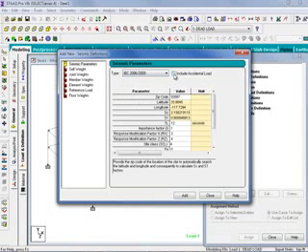Adjacent to the code selection, we will find our Include Accidental Load checkbox. The accidental load parameter prepares STAAD.Pro to calculate and apply torsional loads to account for code-specified accidental eccentricity. In STAAD.Pro, you can only include one seismic definition per model, so if any of your seismic load items wish to include accidental load eccentricities, you should select this checkbox. We will then complete the rest of our seismic parameters.